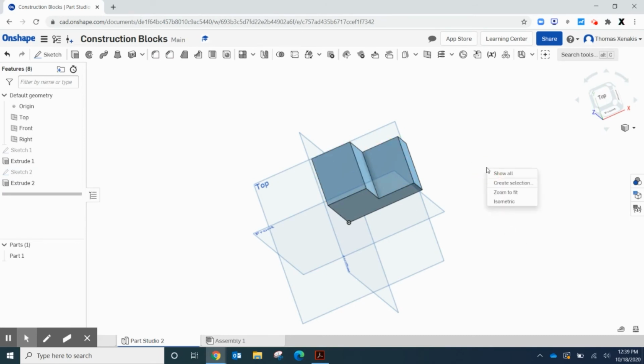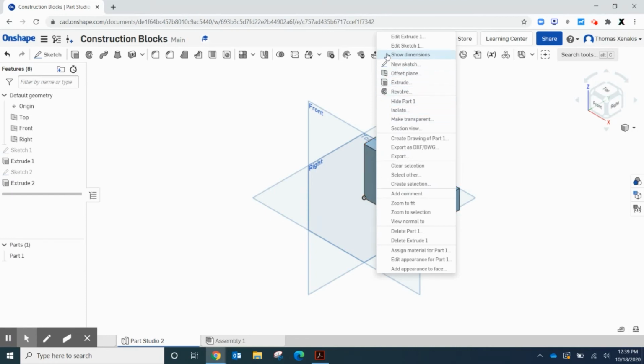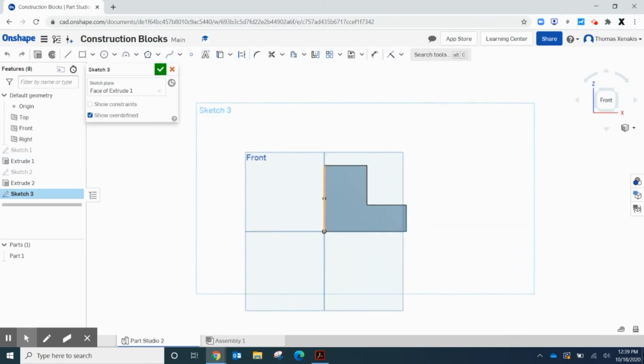Rather than adding on to it, we were able to create a sketch and then extrude, but extrude with a remove to remove that. So when you go to create the arch, that would probably be a good way to do it. Now let me just show you another way here. I'm going to go back and create a new sketch just so you can see from reference on how you would actually do it. So new sketch, again, N is normal.